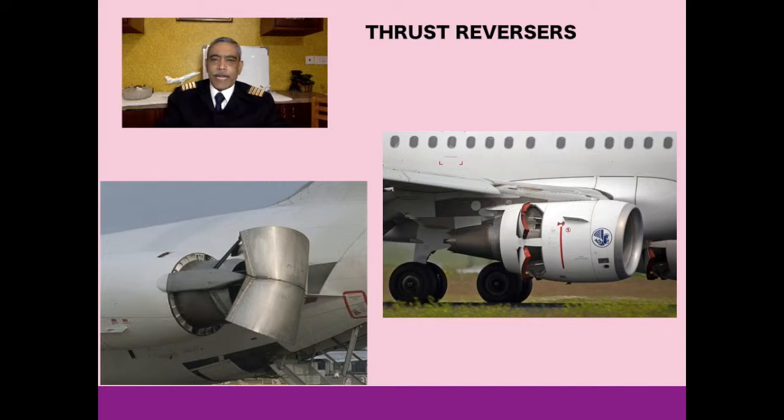A similar principle is employed in the other type, except that the stream between the compressor and the turbine area is directed towards the front, the direction in which the plane is landing, which provides the retarding effect. These types of thrust reversers are very popularly employed in all the airline jets, and the bucket types are incorporated in smaller business jet type aircraft.